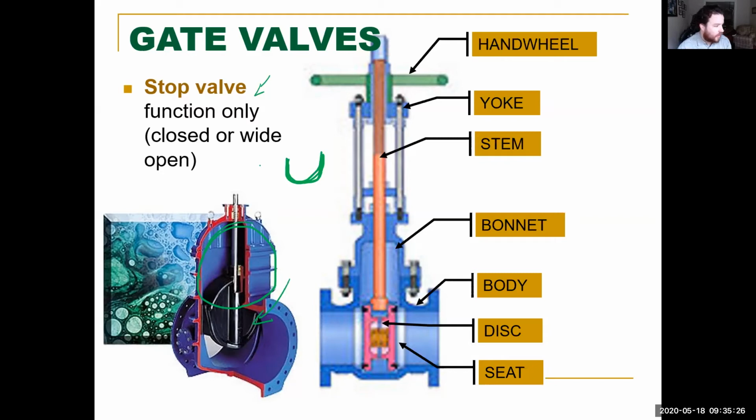When I worked on dredging, it could be a mixture of sand and water going through it. And that just increases the erosion. Slowly but surely, it will erode the bottom part of this disc, because as water pressure hits it and goes underneath it and around, filling the whole cavity, it's going to slowly erode some of the metal.